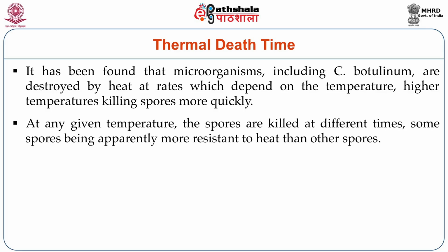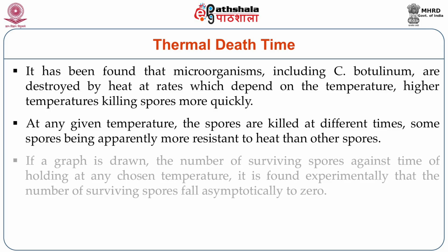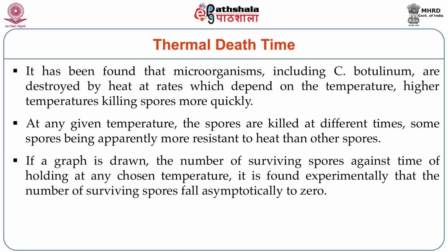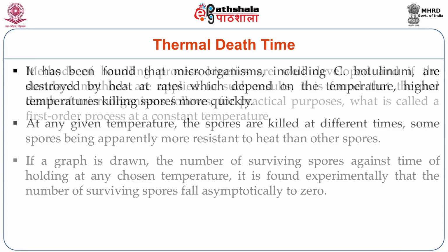At any given temperature, the spores are killed at different times, some spores being apparently more resistant to heat than the other spores. If a graph is drawn of the number of surviving spores against the time of holding at any chosen temperature, it is found experimentally that the number of surviving spores falls asymptotically to zero.